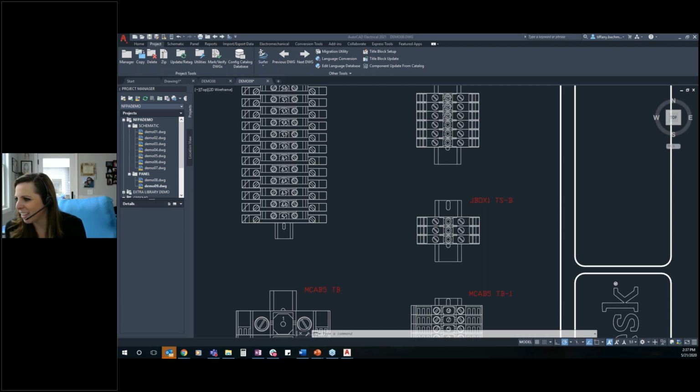So another question here: can I use electrical symbols from all electrical standards like IEEE, IEC, NFPA, or can only one standard be used during AutoCAD installation? So you can install all standards, and you should if you are going to be using them. If you sometimes do drawings in imperial format in the US, but then other times you need it in metric format, you should definitely install NFPA and IEEE. If you are doing a lot of work internationally and use IEC symbols a lot, those are important things too. So you should install all of them.